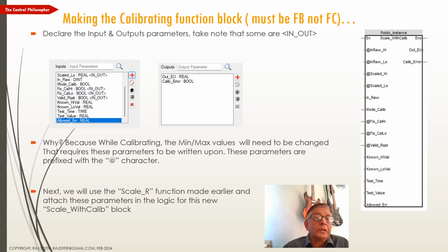scaled output signal. So we also need some values for comparison, that is, for let's say a known pH or a known temperature, for typically 2-point calibration. So this example is for 2-point calibration. The principle can be expanded to any number of points that we will handle in a later video.